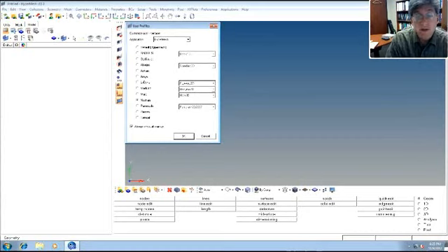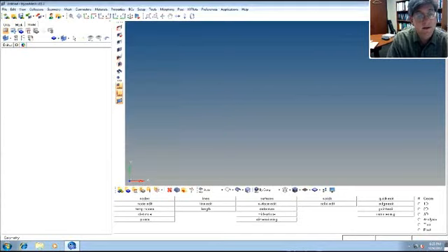Here you can see you can pick a variety of software. When you pick one of these, it changes a little bit the way Hypermesh works so that it supports the actual cards for that program. So we're going to do Nastran. Actually, OptiStruct is very similar to Nastran. Okay, so we hit OK. And if you want to use OptiStruct and solve it directly in here, that's probably okay for this problem